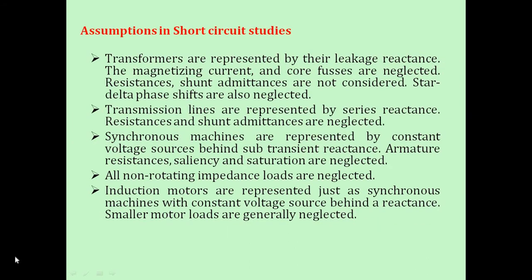Assumptions in short circuit studies: transformers are represented by their leakage reactance. The magnetizing current and core losses are neglected. Resistance and shunt admittance are not considered. Star delta phase shifts are also neglected. Transmission lines are represented by series reactance. Resistance and shunt admittance are neglected.